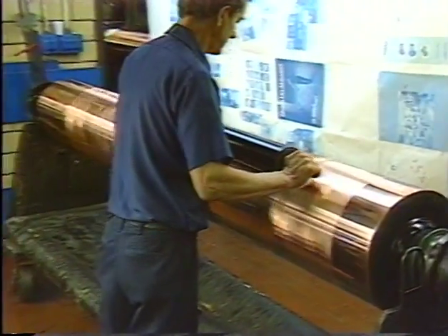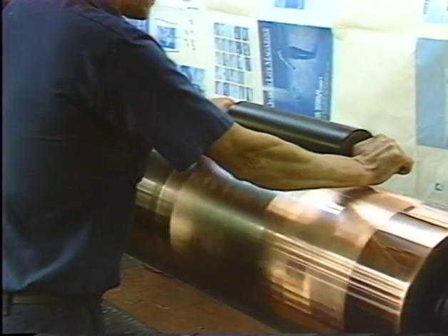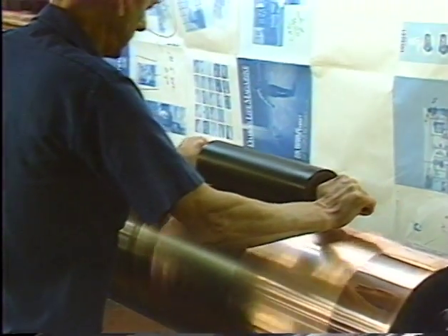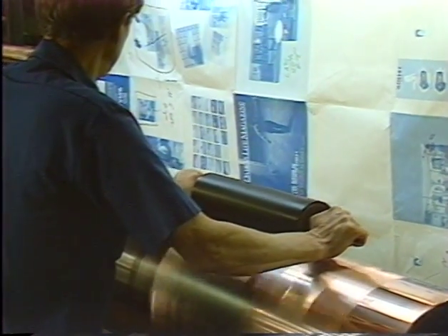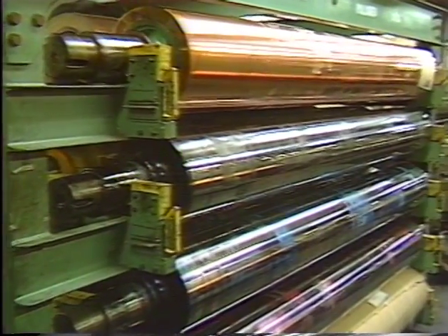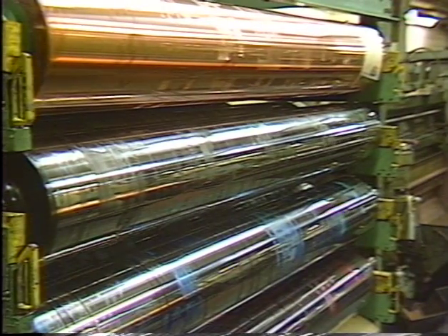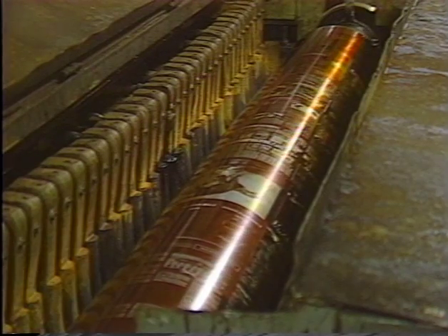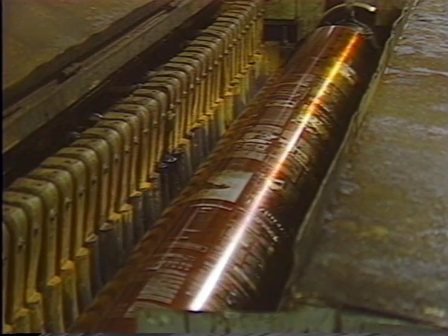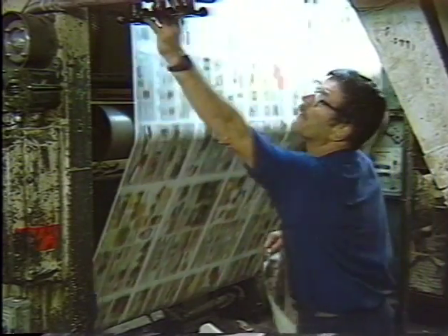The term photogravure indicates that photographic processes were used in preparation of the printing plate, and rotogravure is used to denote that the press used for printing is a rotary press. Cylindrical plates for commercial rotogravure printing are expensive to produce, but exceptionally durable. Long runs ranging from 1 to several million copies are possible with this process. Long runs are necessary to make the process cost-effective.